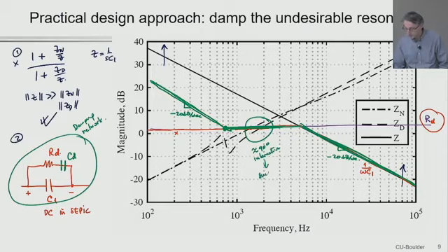So small effect on the correction factors and thereby the transfer function of the converter. At high frequencies, this does still behave as a capacitor, and at low frequencies, it does behave as a capacitor of larger value, right? So this here is going to be 1 over omega (CD plus C1).